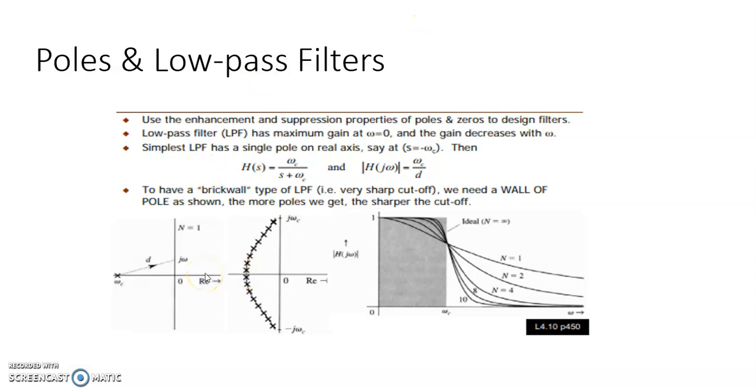Now talking about the characterizations. Based on that, your basic 4 filters are in your syllabus. Talking about the positions, first we have the low pass filter. This type of filter passes the frequency from 0 up to some design frequency called the cutoff frequency.